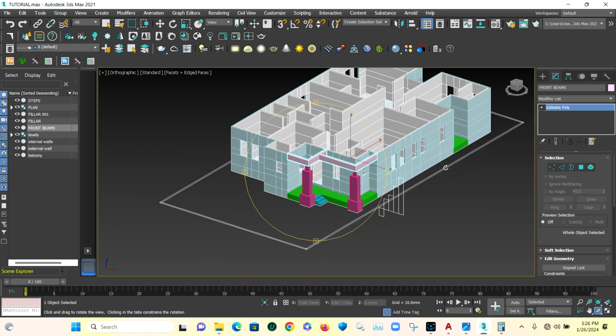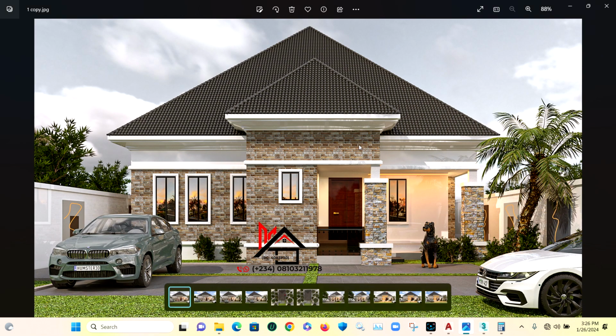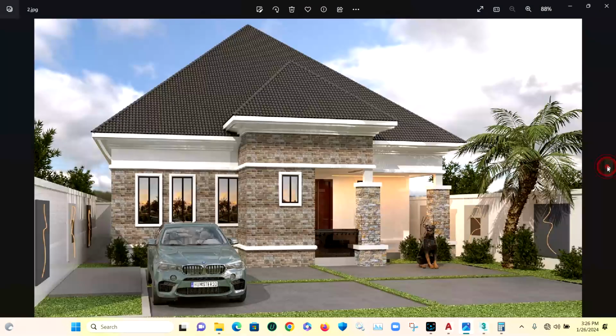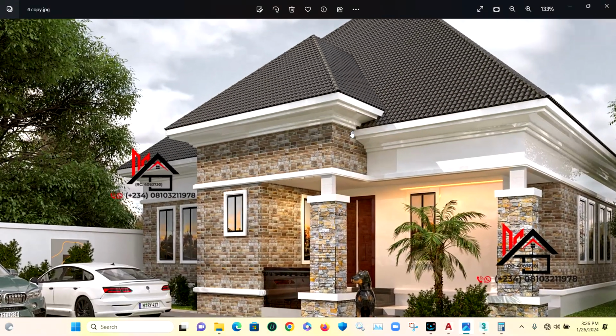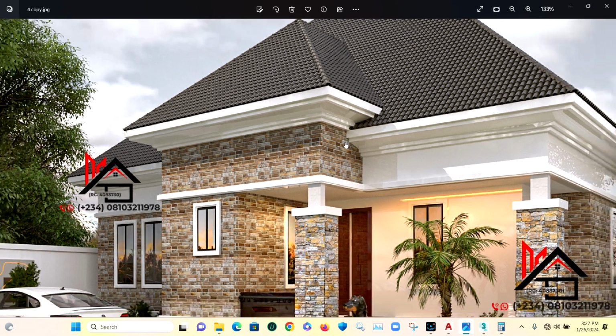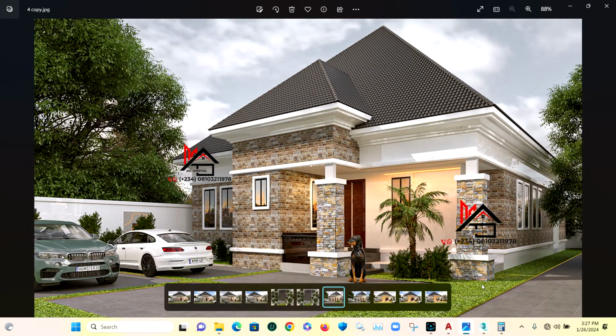Now if you look very well on this plan, look very well on this 3D, you see that this was above this, but then you don't know the exact height with which this went to this. You just know from here that this one started immediately after this parapet. So for the meantime, I can just make it go above this. Then when it's time for my parapet, after drawing this particular parapet, I will see the height of it, then move this one to that height before I attach this parapet. Now I hope you understand.